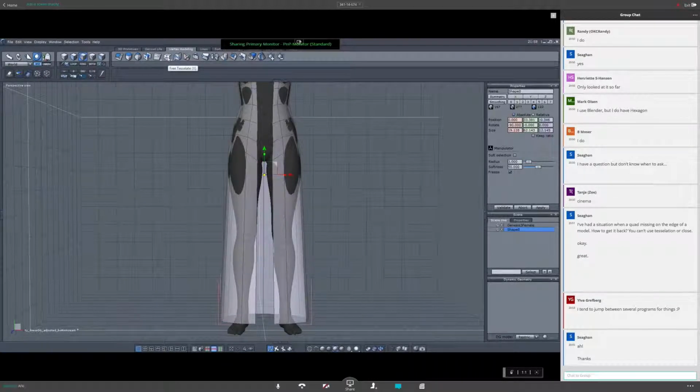So there are different tessellate tools up here. This one is for manual mode, where you can place your points and edges the way you like. Another one, this tessellation by slice tool, does it differently. If you press Shift, it places your little square down here, which turns red, right in the middle of your selected edge.